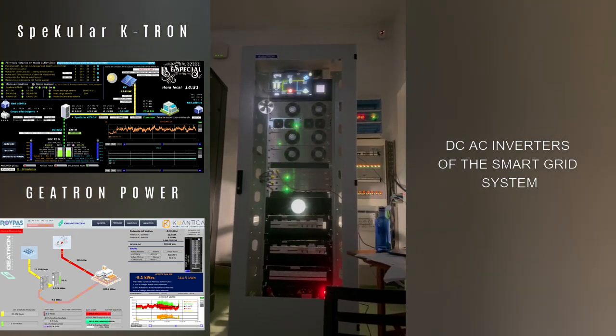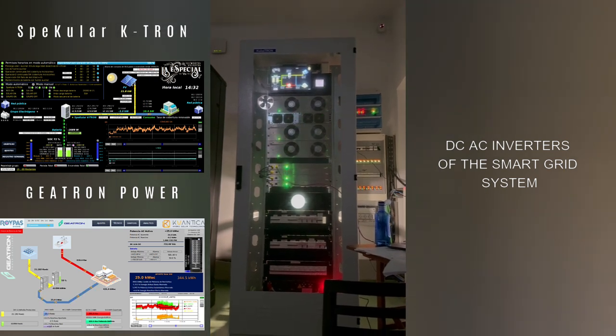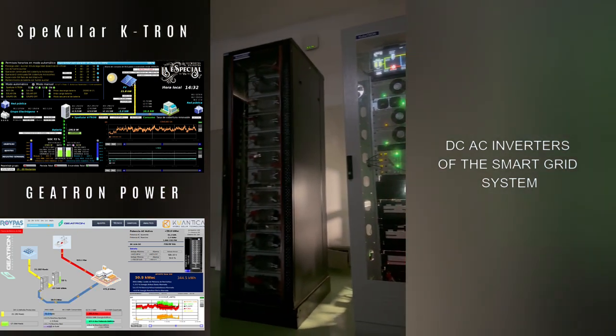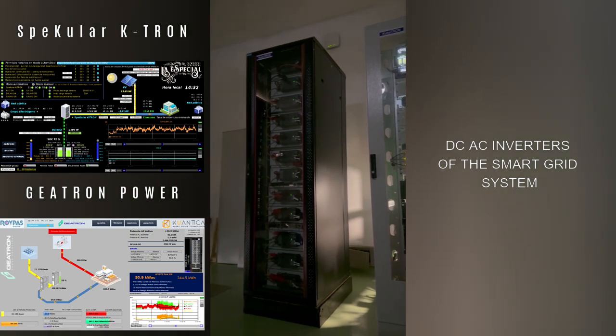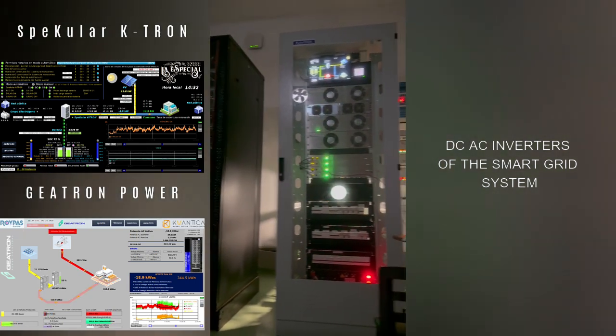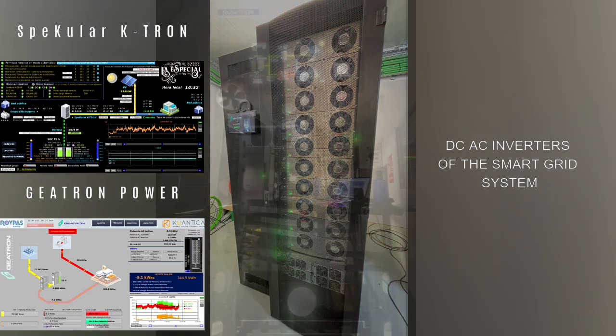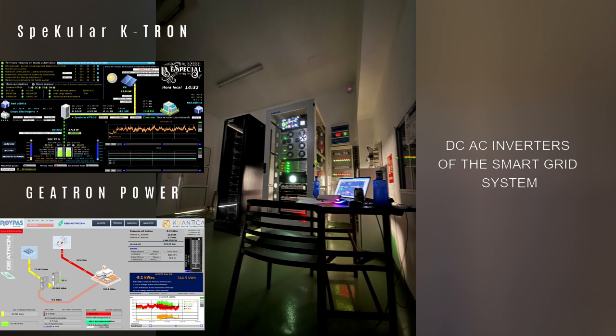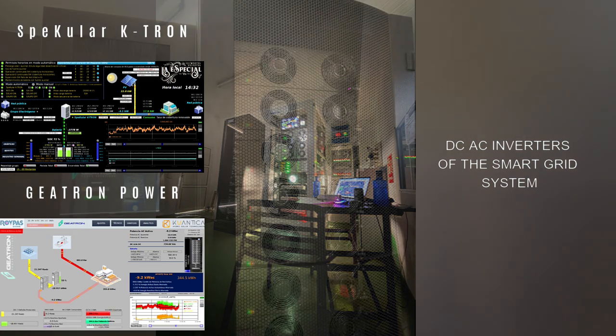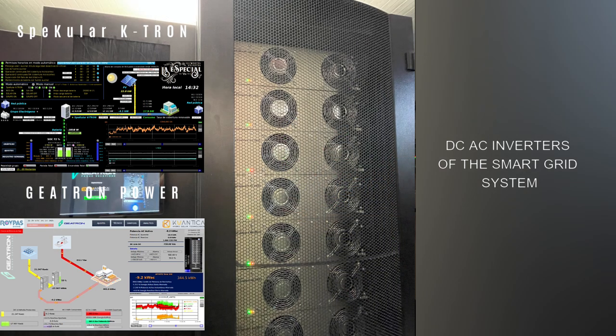Capacity to operate in parallel with the grid as current regulation or voltage regulation, grid following, or isolated from the grid as voltage regulation, grid forming. In voltage regulation mode, it is capable of replicating the behavior of a synchronous machine, creating a completely isolated and independent network, operating in parallel with an electrical grid, raising the voltage from 0 volts (black start), interconnecting several DC-ACs in parallel without them having to communicate with each other thanks to the internal droop function, and generating a virtual DC-AC impedance that guarantees the necessary attenuation for parallel connection.